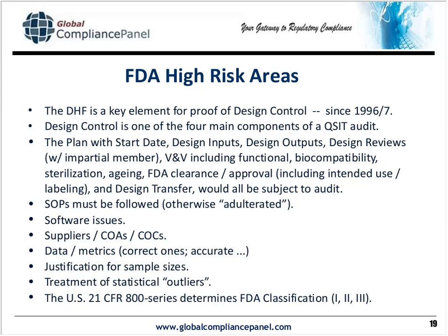There are a few good references out there, and the one I like to go to is Juran and Gryna's Quality Planning and Analysis, and you can get several editions used off of Amazon or elsewhere. And I quote directly from a page that talks about N equals 30. And I cite that particular book as my justification, and I include that justification in the validation documentation if I'm using N equals 30.